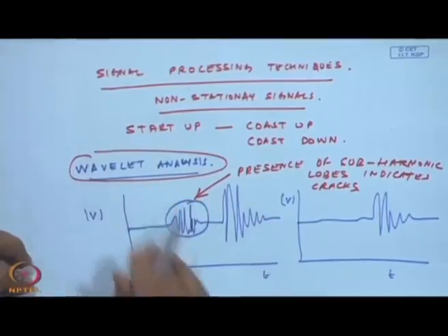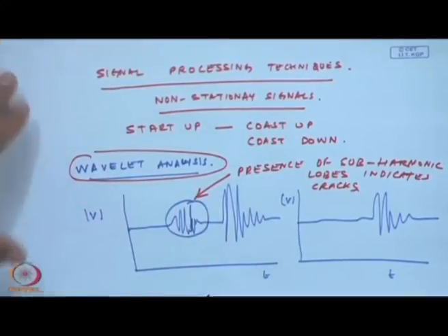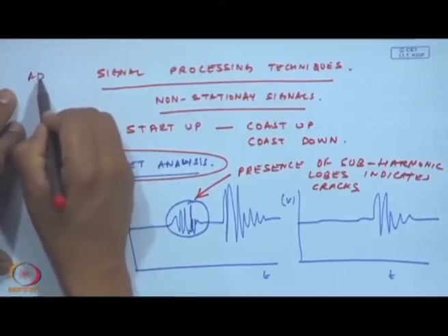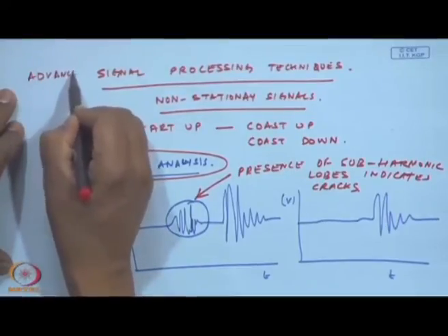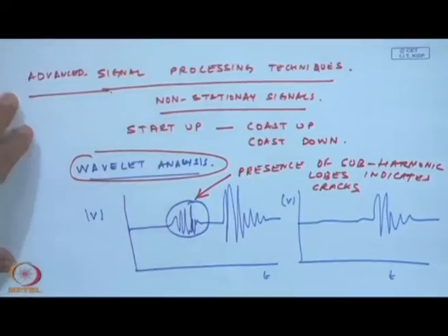Though in this course we are not going to discuss wavelet analysis, through advanced signal processing techniques we can also detect cracks. Earlier, people were never monitoring cracks through such vibration monitoring. They only did an NDT test, either through ultrasonics or dye penetrant, to locate cracks. But nowadays, with the improvement and the understanding of the science, and these algorithms having come up, people can find out the occurrence of such cracks in such systems.